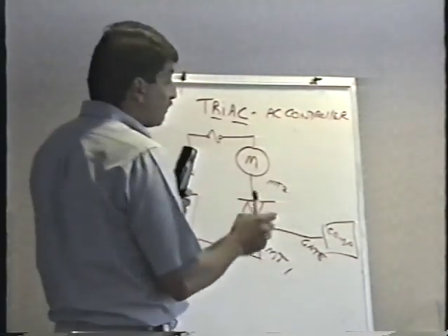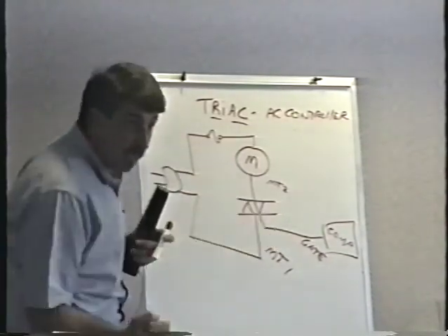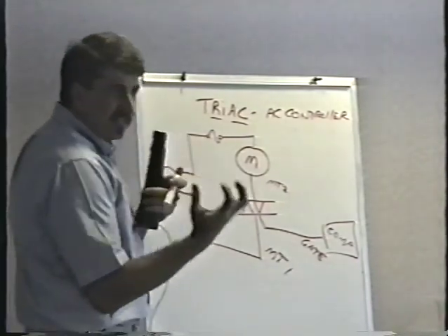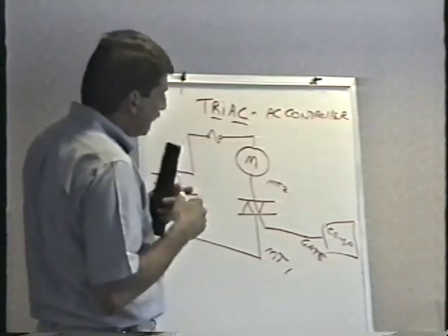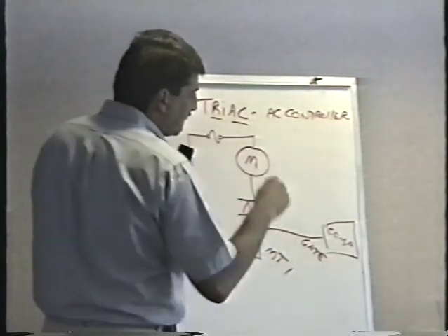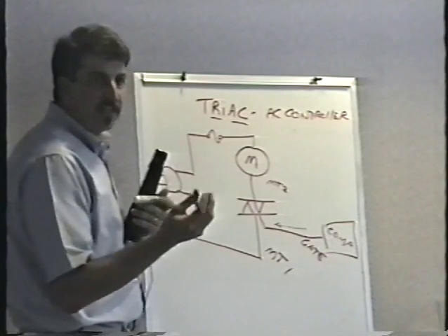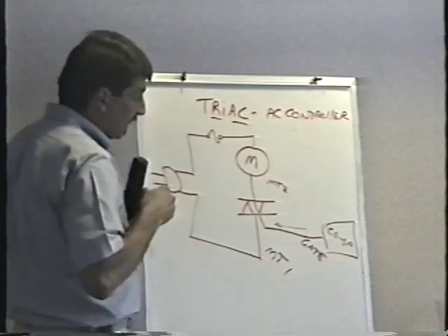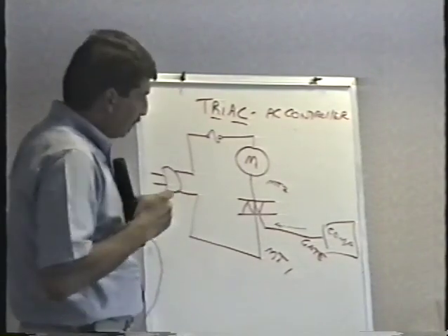When the computer wants to raise the bar, or in a skee ball machine, energize the solenoid to let the balls come down, or anything that needs a massive motor or a big coil, instead of using a transistor, we use this triac. When the computer wants to energize the thing, the motor, the solenoid, whatever it is, it simply sends a teeny tiny amount of voltage and current out to the gate. It's very sensitive. The gate's very sensitive. That energizes the triac. It's just a switch. It just closes the triac. In other words, it shorts out right across the triac, completes the circuit.